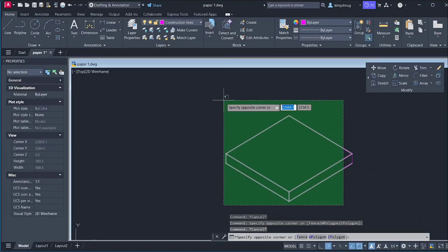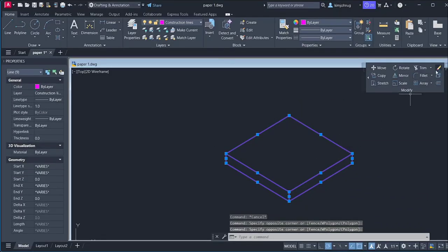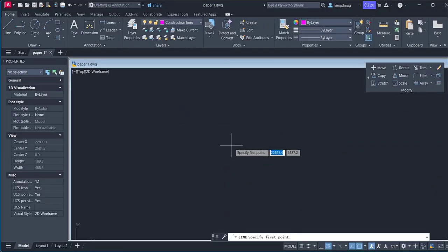I'm reading from the top, let me unselect everything. The erase tool. So my first line is 100. So I've set my scale to millimeters. So 10 is millimeter. And the angle, polar tracking is there.